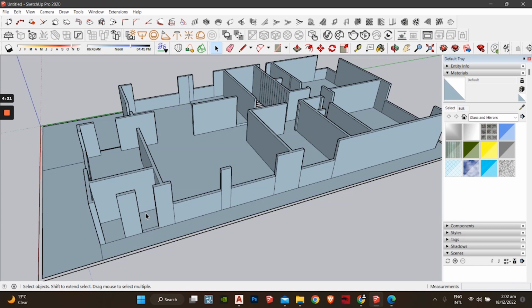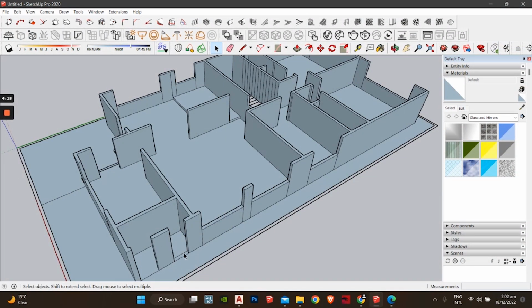Okay, now these are bathroom ventilators, right? So usually if you have a height of 11 feet, the ventilator is going to start from 8 feet. If you're going to have a 2 feet ventilator, it's going to start at 8 feet, end at 10 feet, and you'll still have a foot left, right? If you're dealing with an 11-foot high ceiling. But since we're only using 7 feet to represent our walls because it's easier to see in a 3D floor plan, we're just going to leave it at, let's suppose, 6 feet, right?